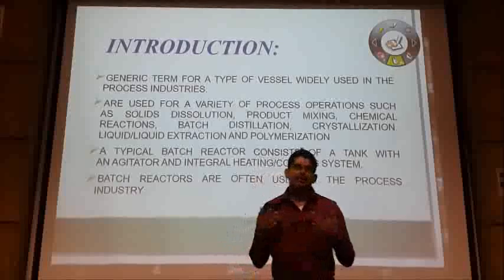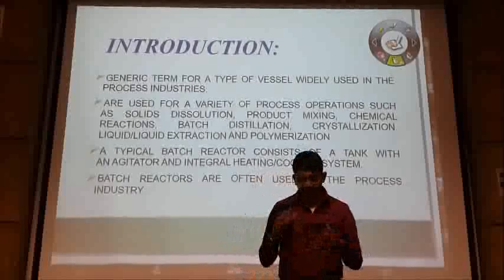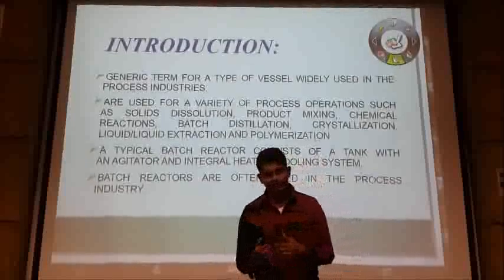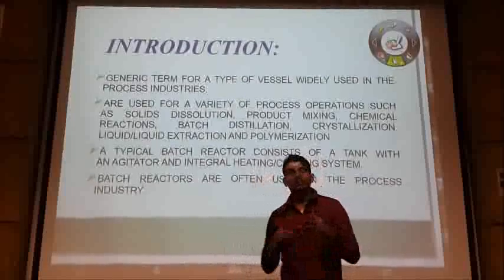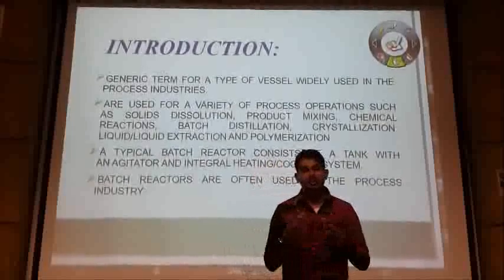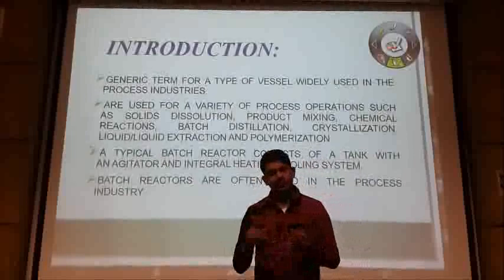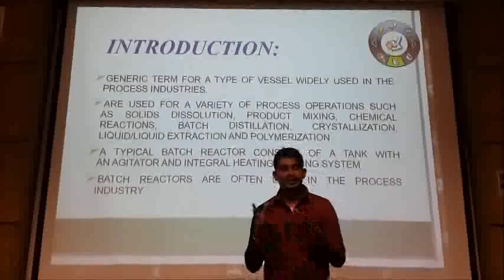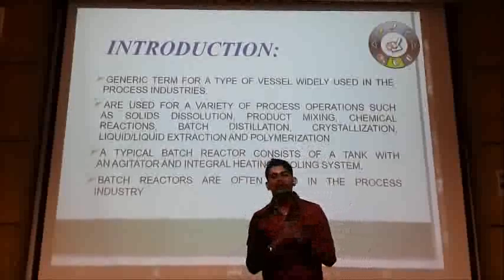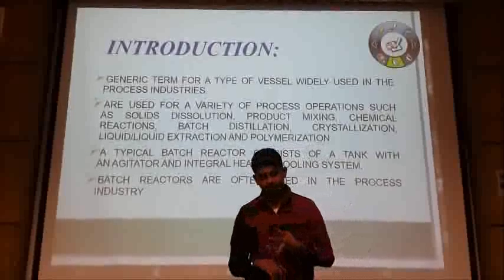Within the chemical and pharmaceutical industries, external jackets are more preferred because the vessel can be easily cleaned. The external jacket can be defined by 3 parameters. One is the response time to modify the jacket temperature. Next is the stability of the jacket temperature. And lastly is the uniformity of the jacket temperature.